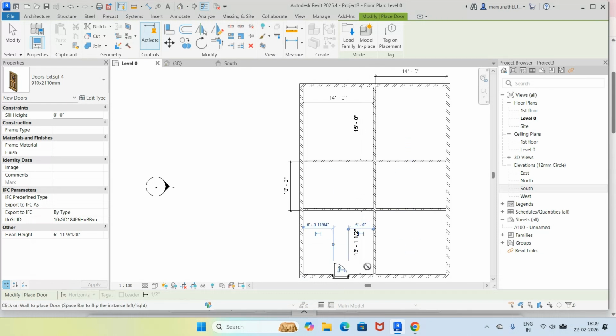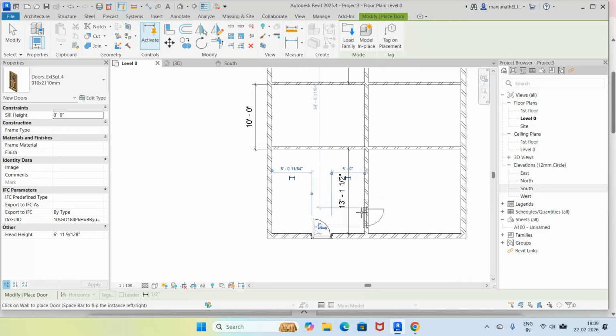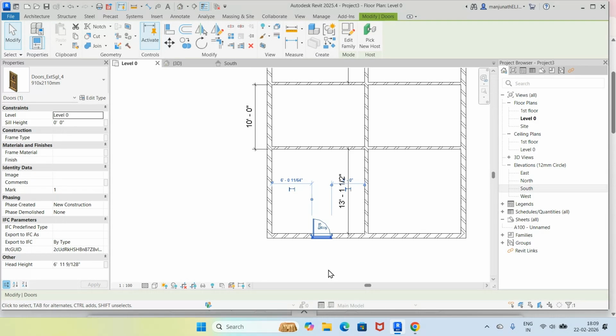And the moment you see here, you can see that either I can open from the left. So you have two things here. So I will cancel this. Now I have the door fixed. So once the door is fixed, I will go for modify and click on this. Okay. Now, if I take the door outside, you can take it from outside, or you take flip outside.